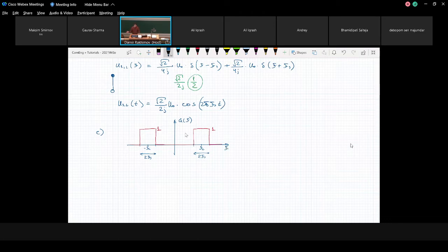When you calculate the equivalent transfer function in the low pass range, you do the same steps. You remove negative frequencies, you shift by the corresponding frequency, and that's all. Don't do normalization. You don't need normalization because you don't have a notion of energy. You just need to have the same amplitude.